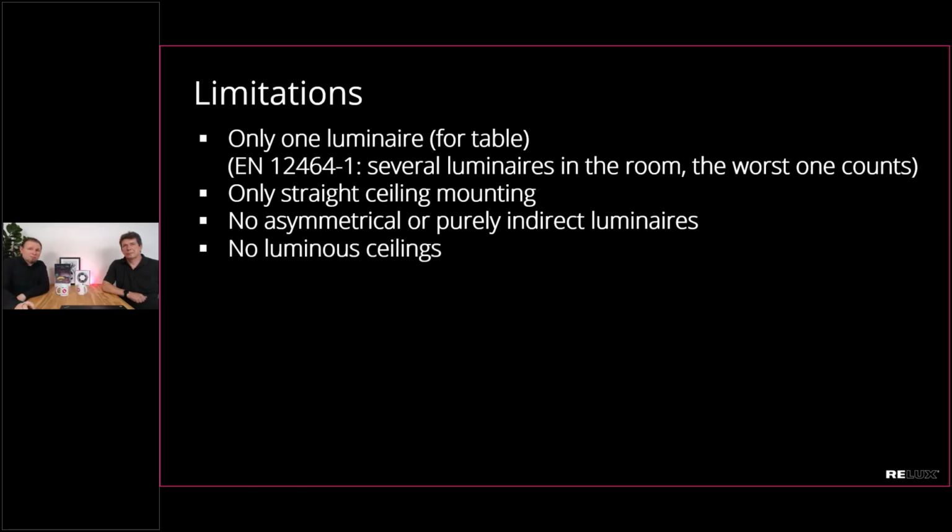Then also not applicable are luminous ceilings. So if you have a ceiling which is just diffused glass or plastic, large luminaires, or the complete ceiling as a luminaire, it's also not applicable. And in this situation, you don't have to deal with glare in general. So this is just not glary, which is good. So you do not need to have these UGR values if you have this situation.